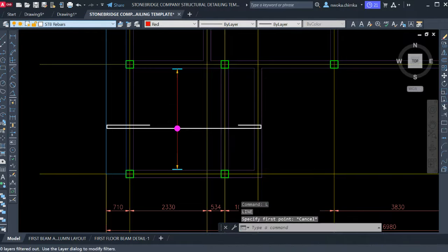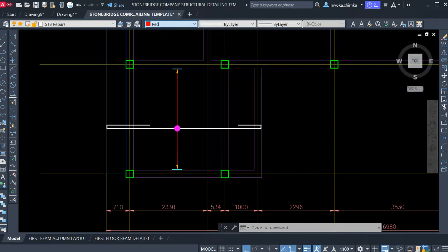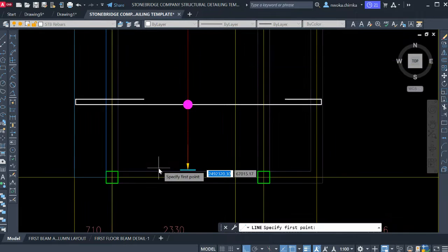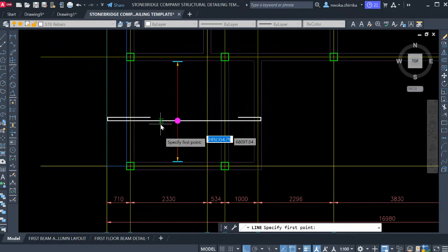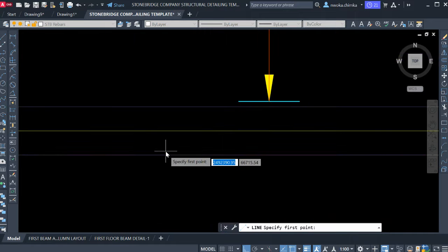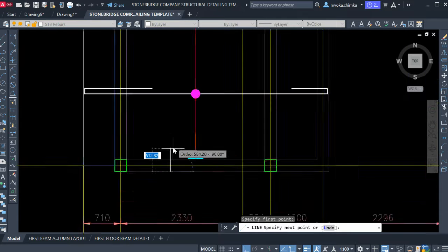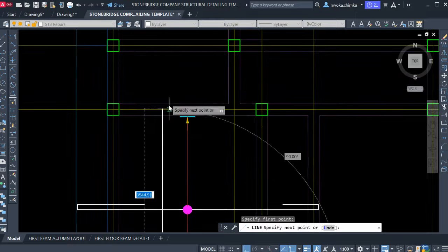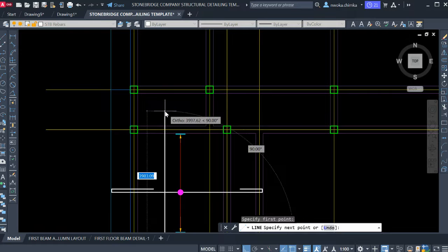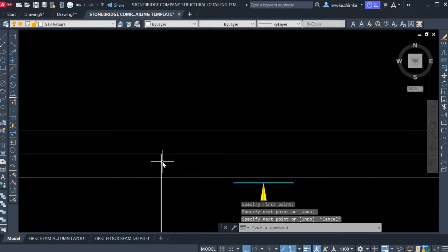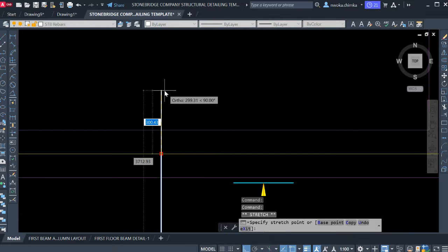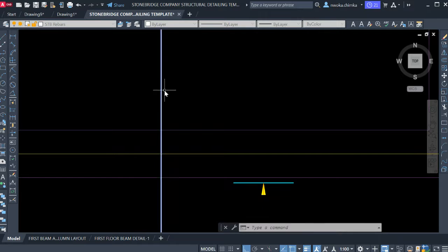so I'll go back to this place and STB, and then go and select my rebar right here, change this to by layer, and then click on this place. Now I want to draw my vertical reinforcement, which is the distribution reinforcement. So I'll click on this right now, and then go across this a bit. Click on this place right now, this middle, and then click on this point and type 600. I've already explained to you what this 100 means, and then I click and say enter.